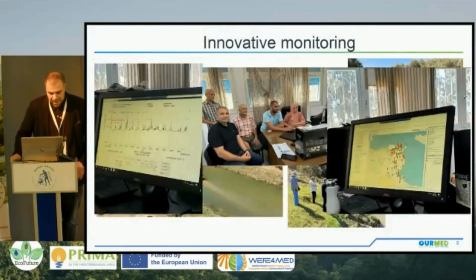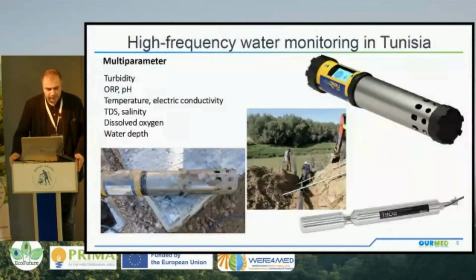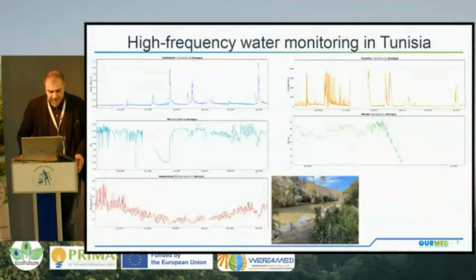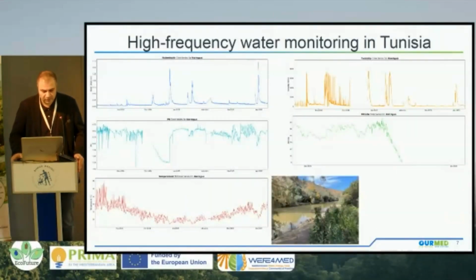So monitoring, I think we share, we need data, we need innovative monitoring, so we need also to do it with local stakeholders. We can benefit from this next generation of high frequency monitoring. However, we have to tailor it to the context. For example, here we installed a sensor in Tunisia, but you can see after 1 week, it was full of sediment due to the sedimentation, and we have to be creative in how we can deal with this kind of critical condition. So data has been generated.